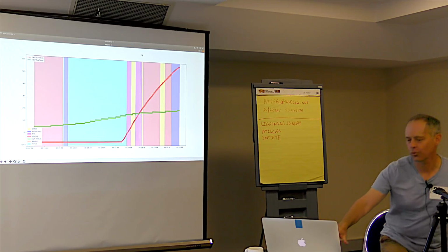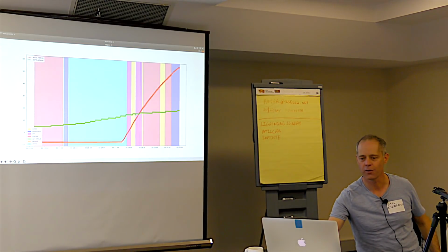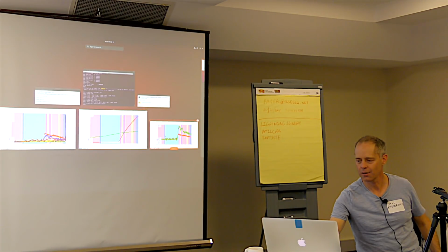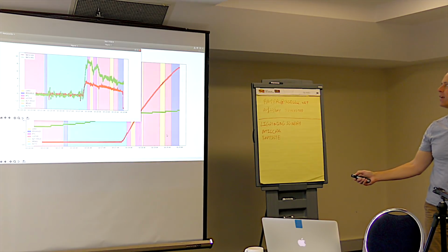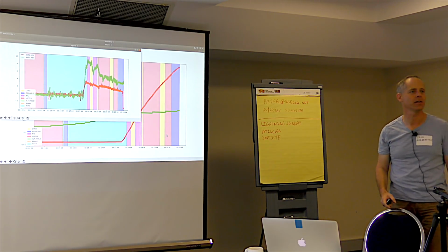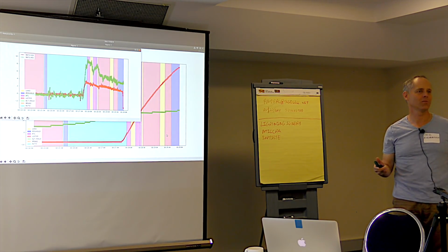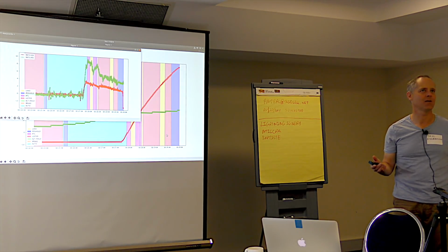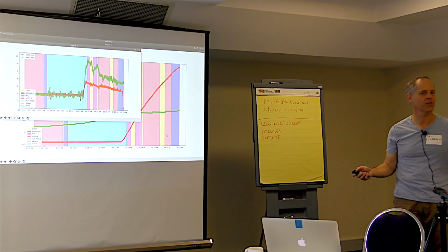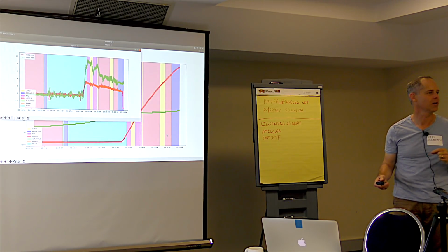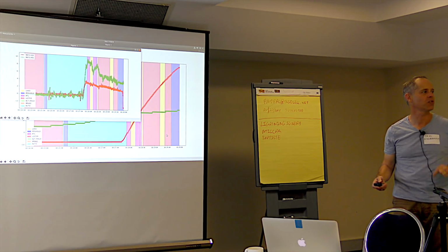And this is also consistent with when we have a look at the innovation readings. We can see that they start off large, and then towards the end of flight they're slowly coming down as the EKF's learning that offset. So all we can infer from this data is that for some reason that sensor axis developed an offset, a sudden step change in offset mid-flight. Just came unstuck.